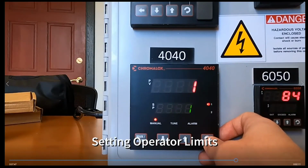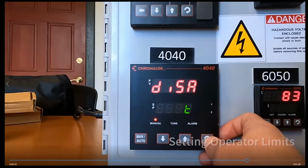Okay, so this is cycle time. The default for this, especially if it's an SSR, will be 1, as in 1 second. If you have a customer and they have a contactor and it's burning out really quick, I would take a look at the cycle time and try to get it as large as possible, just so that the contactor isn't continuously switching on and off and wearing out its mechanical properties.